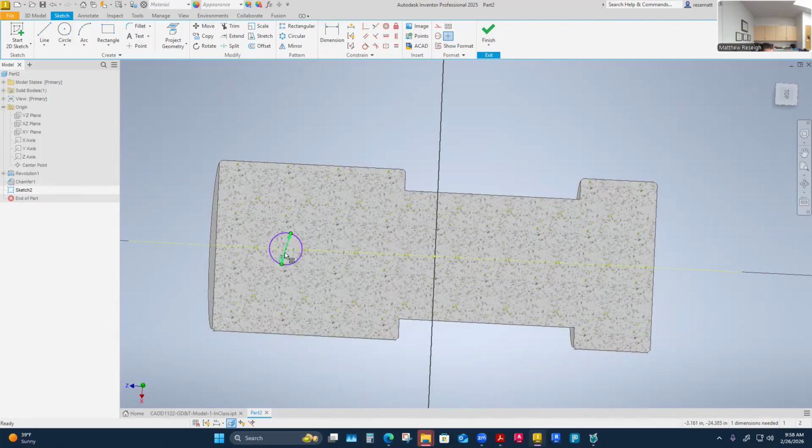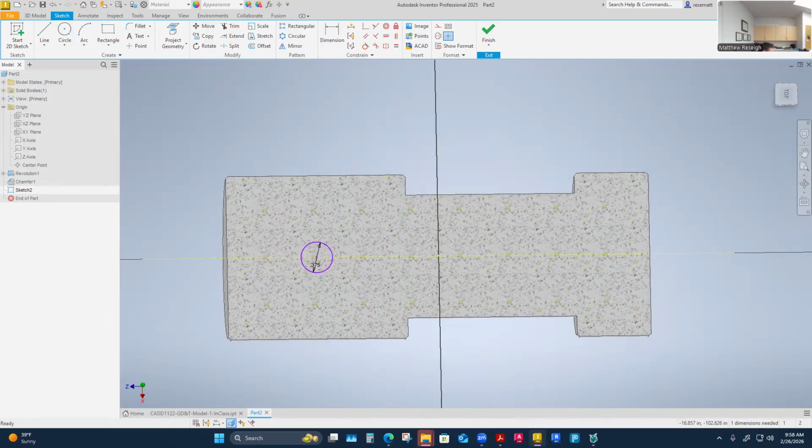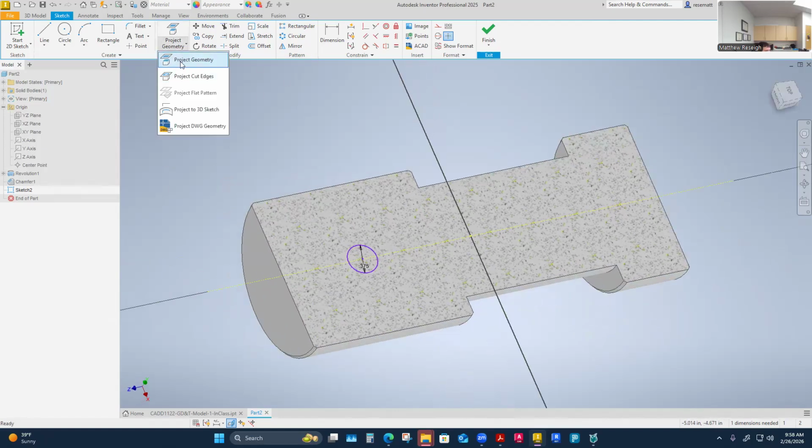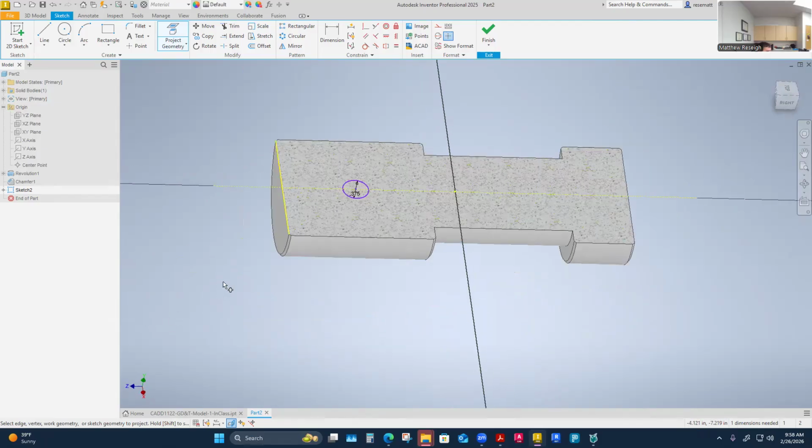And then I just need to look. So this is like bound by this. I can't get it off that now, but I need to locate it along the Z axis here, which has a datum from this end here, 0.5 over to where that's located. So I'm going to go ahead and project the end of this right there. I can just select this. This will become a line. This is the end surface, right? It becomes a line like that in a projection.